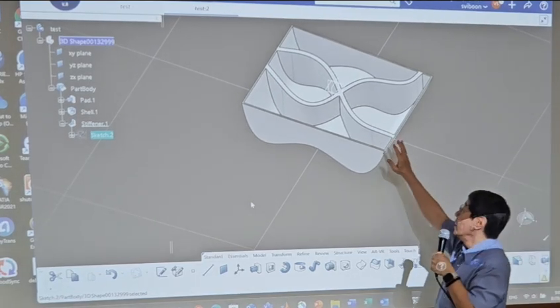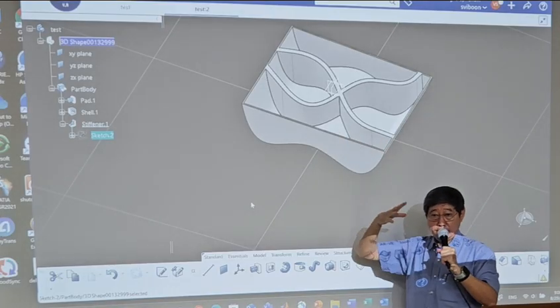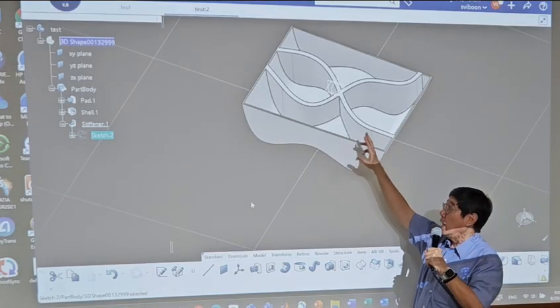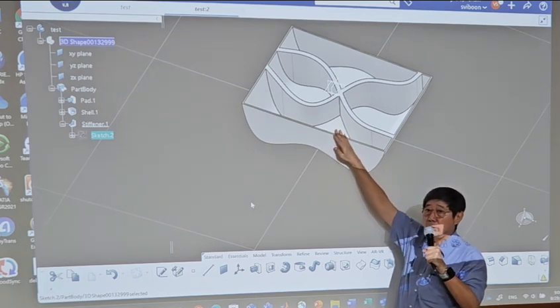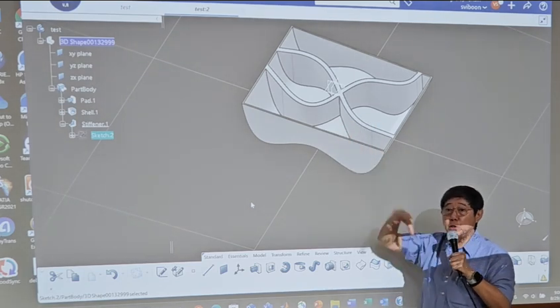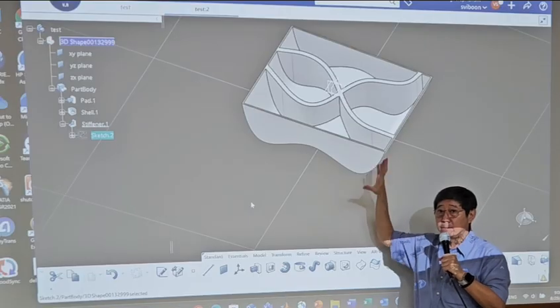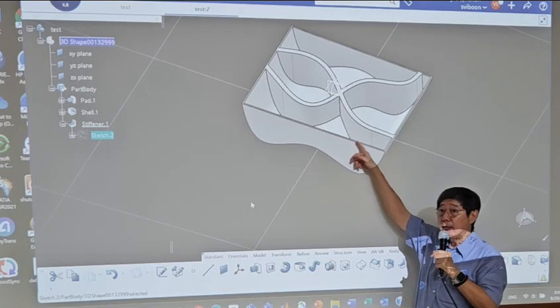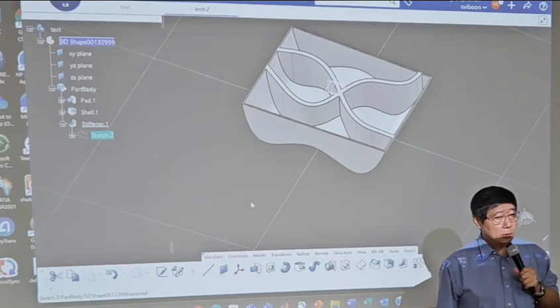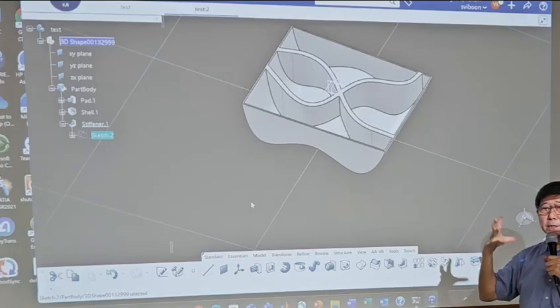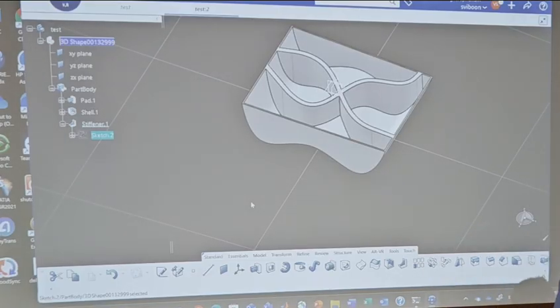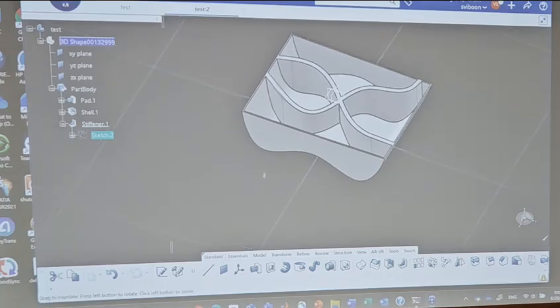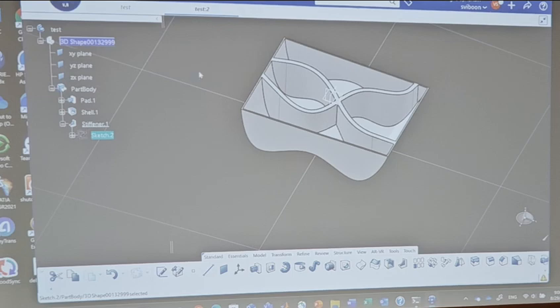Sometimes, if you make this one solid, instead of solid, I mean you have this type of stiffener, you can reduce a lot of mass. At the same time, your part is very strong, I mean stiff enough or equivalent to the solid one. So this is used quite a lot, especially in plastic design. That's a stiffener. One thing that you're going to have problems with.